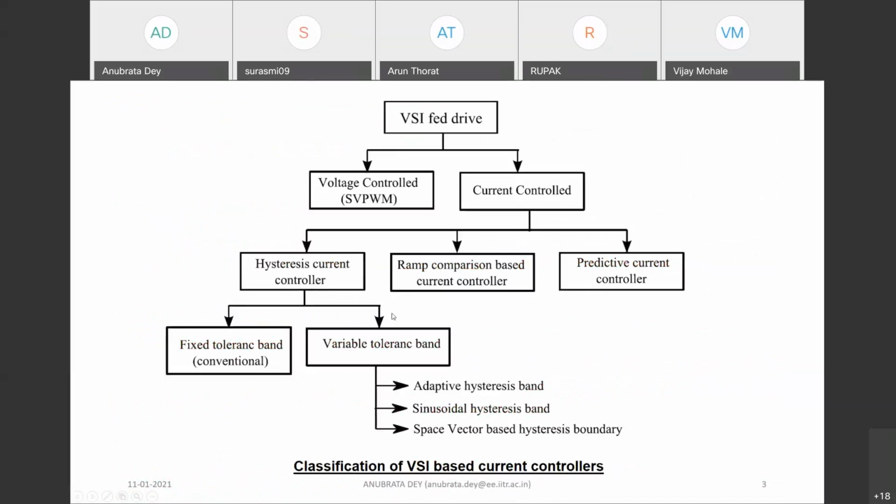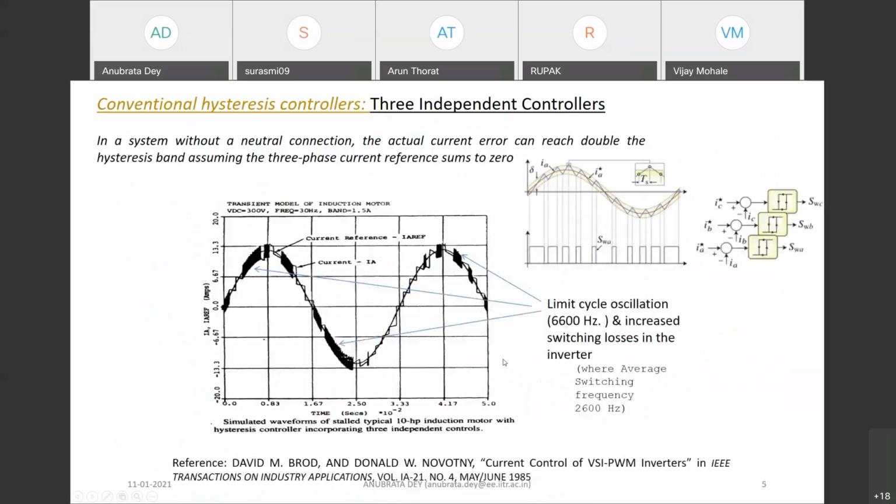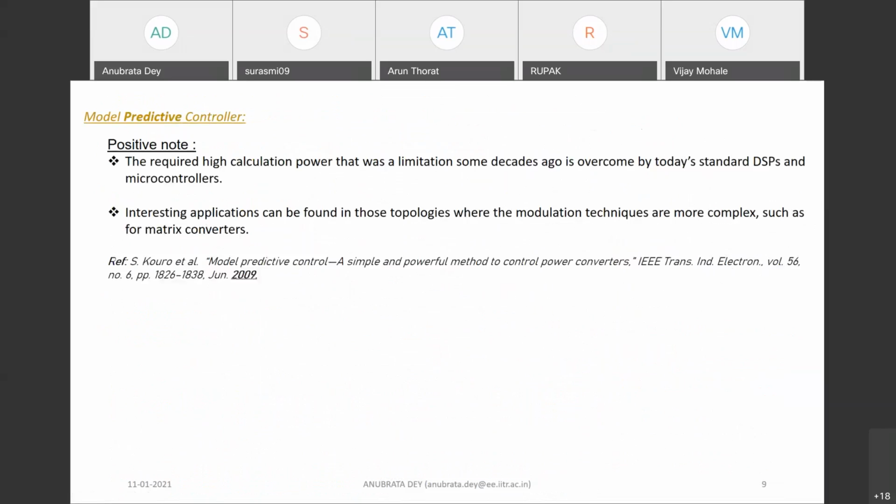They have a problem because, apart from their inherent problems, they cannot work with multi-level inverters. Nowadays multi-level inverters are coming, and there are many voltage levels at the output, more than two, so it is not very simple to control the current. On a two level inverter, you either switch on the top switch, so current will rise upward, or you switch on the bottom switch, and current will fall downward.